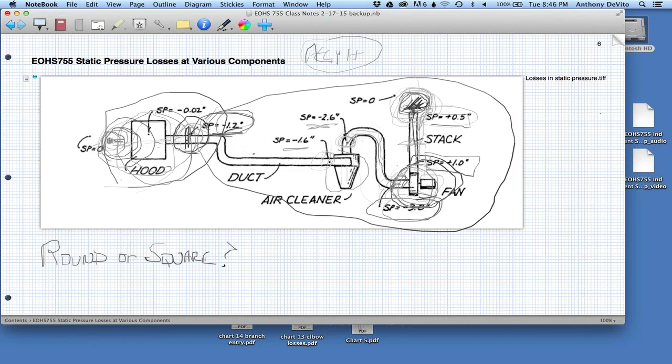And in addition to that, the air with the contaminant, or whatever remains of the contaminant, hits the rain cap and gets directed back downwards, right? Which kind of defeats the purpose of putting it so far up. So rain caps, when you play the PowerPoint, you'll see that Jeff Burton is not a very big fan of them. If you look at exhaust systems, usually you'll see some other kind of accommodation for dealing with rain, rather than a typical rain cap like you might see on your furnace or something like that. Okay, let's move on.